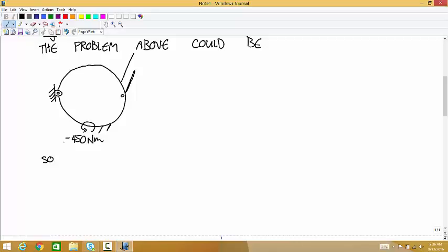You know what I mean? And so that's a couple. Think of it as a moment with a component in the z direction or negative z direction when you're doing 2D problems. Just like any other moment is. And it doesn't produce any force because the forces are equal and opposite, so they cancel each other.